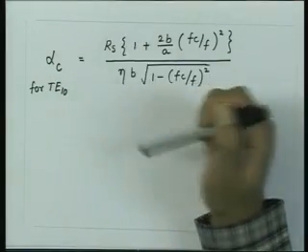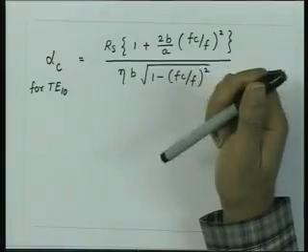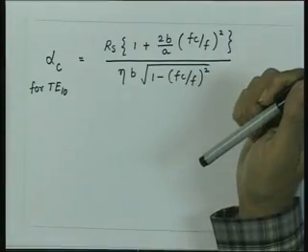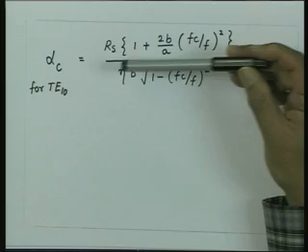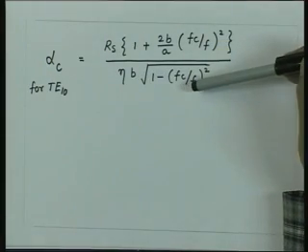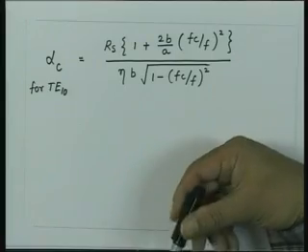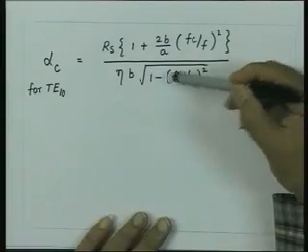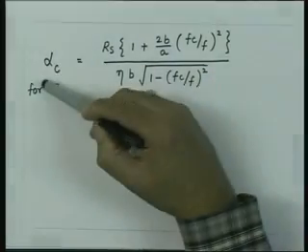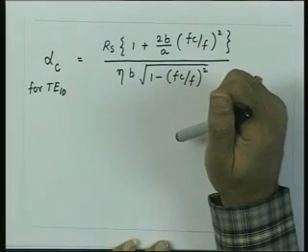So, as you go to higher frequencies you get more losses inside the waveguide, but we also note that the attenuation constant now is also a function of frequency relative to the cutoff frequency, and as the frequency approaches the cutoff frequency, again the attenuation constant becomes very large.